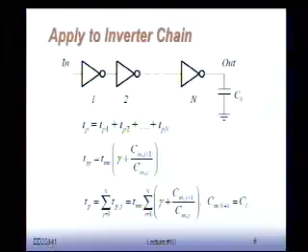Now, let's go to the next step. Suppose now that I'm saying, well, gee, I'm going to make my problem a little bit simpler. Just let's say that I assume that I have n inverters between my input and the output, load capacitance. N being any fixed number, 2, 4, whatever it is. Okay? So now I'm going to try to figure out how I should size those n inverters in such a way that I minimize the propagation delay between in and out.